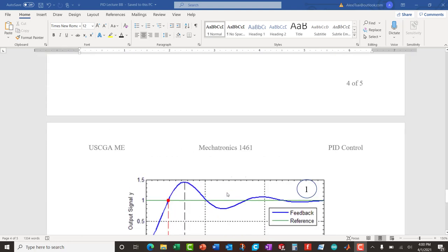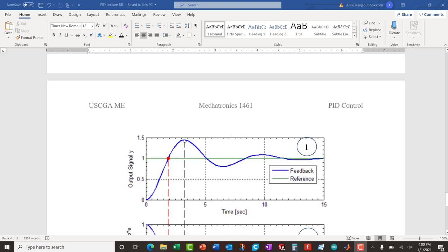Now let's imagine for now, this is sort of more like it in terms of the response the ball would experience once it is controlled. Okay, so the y-axis here is normalized, which means I'm just taking the minimum and maximum bounds. 1 is my set point. That's where I want to go. Okay, so in this case, imagine 1 is 5 centimeters. Okay, and I'm somewhere else. So this is what the ball would do in a certain amount of time. Eventually, the blue line where the ball is would match the green line where my set point is. That's the center of the beam.